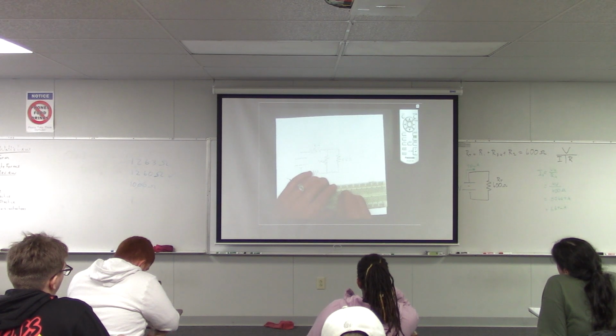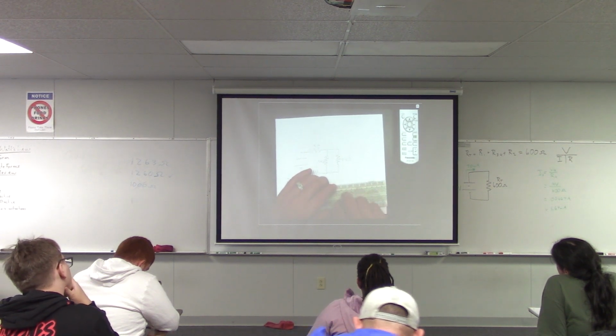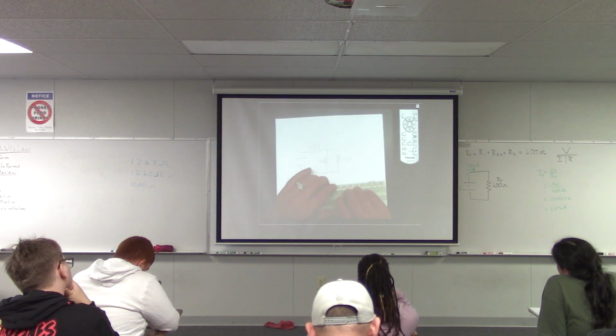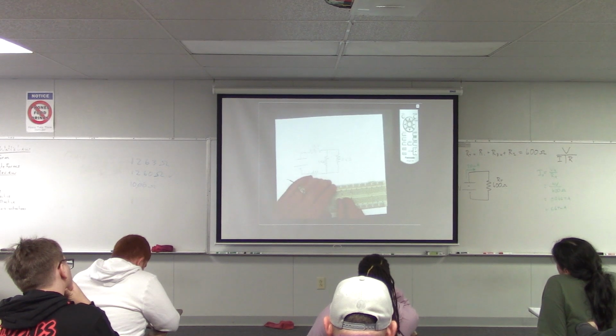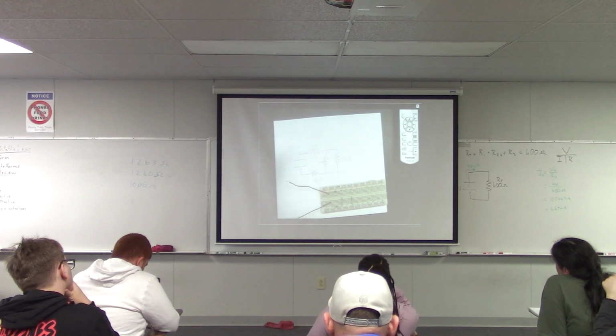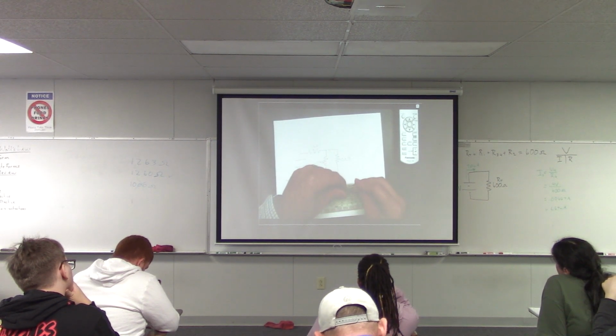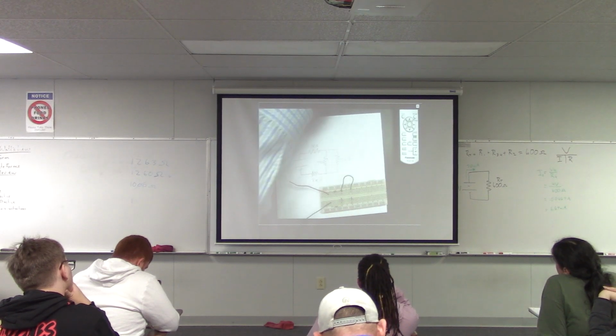And now we need to make a connection between this resistor and this resistor over there. You can see that there are wires that go from the top of this resistor to the top of that one. So we can use a jumper wire for that and make that connection, and the same thing on the bottom.